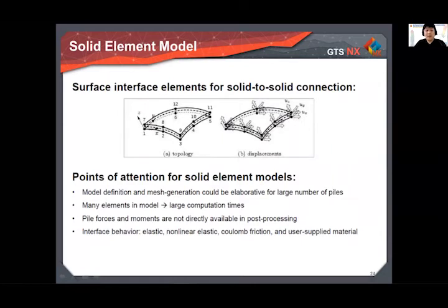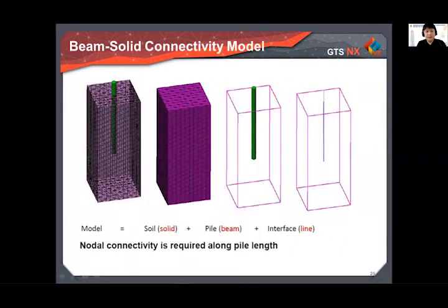This requires a large number of elements in the model, so you have to spend much time on the analysis. This is the reason why we simply use the line element for the pile itself.